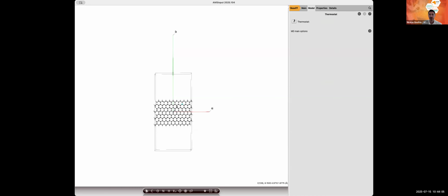I'll put a thermostat, so exactly the same as before. Berendsen thermostat, 300 Kelvin, and then 100 femtosecond. So all of that is written in my slides, so you should be able to reproduce. And then the barostat this time. So I also use Berendsen here. I put 1 atmosphere. The damping constant is in general a factor of 10 with what you put with the thermostat. And I'm just going to change to scale the X direction, right?